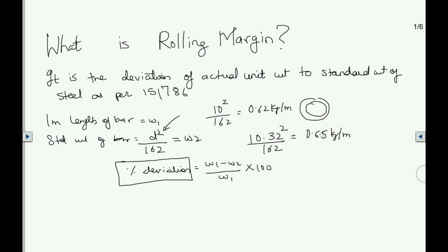A client or a contractor orders the steel in terms of quantities in kgs, as a result of which they will get fewer bars in the bundle than required. The bars come in bundles, so if the weight per meter is larger, then the number of bars, or the length of the bar, will be less than expected. For example, a girder will require a bundle of 10 bars of 12 mm. But if the die was eroded and the diameter of the bars cast is slightly greater, let's say 12.5 mm,